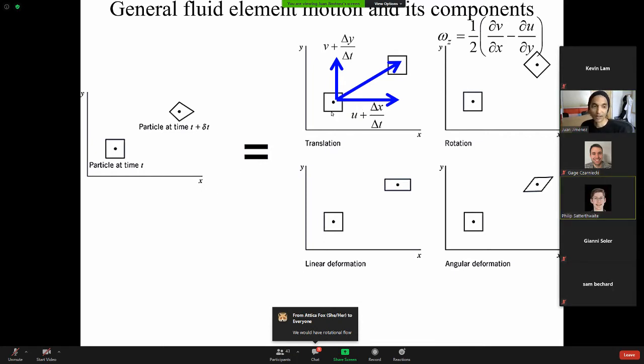I missed the question. So Philip, let's say we said, if we have a boundary layer, we always have rotational flow there. Outside of the boundary layer, like he said, no rotational flow. Why? Because there are no velocity gradients. What about in a pipe flow where the flow is fully developed? Do we have rotational or irrotational flow? It would be irrotational.